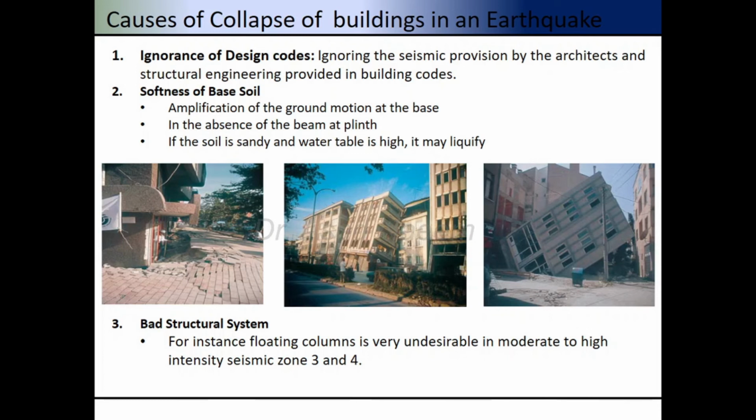The soil exploration at the building site must be carried out at sufficient points and at sufficient depths. Soil classification in various steps of soil and properties like grain size, distribution, field density, angle of internal friction, cohesion, and plastic and liquid limits should also be taken into consideration in the design. Position of water table is also one of the very important factors when designing a structure in a high seismic zone.